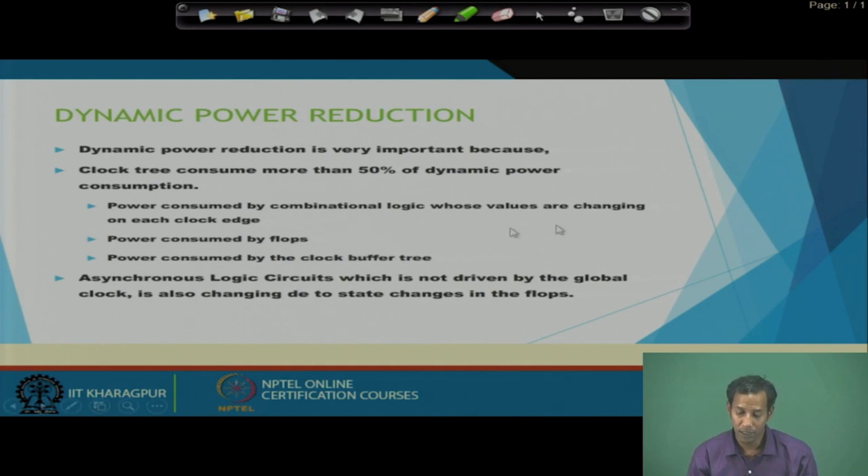And then there is the combinational logic. Combinational logic means that whenever the inputs are available at the input end, the output immediately changes its behavior. Depending on the logic, the output state changes, which creates very fast switching in combinational circuits. Whereas flip flops have to wait for the clock.